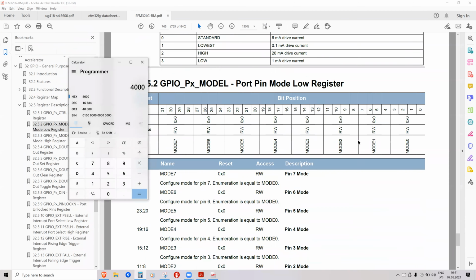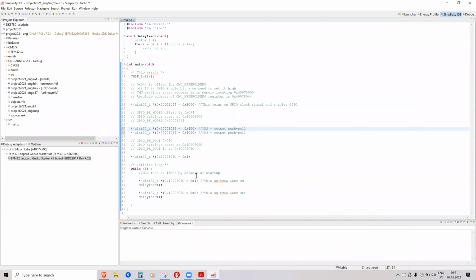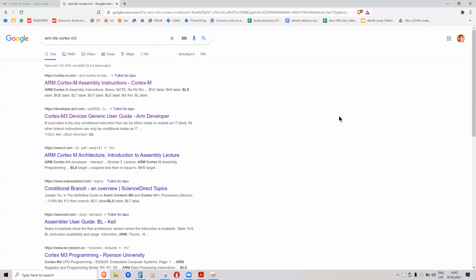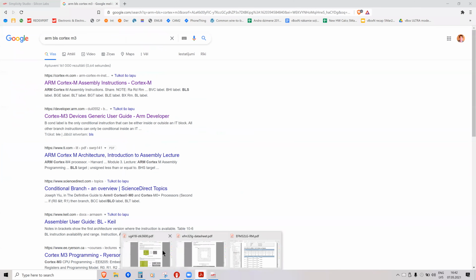And the second option is you can write it this way, but you need to write or equal to 0x4000. In C programming language, this or equal means leave all the bits inside this register as they were originally, but in addition to those which are already set, you also set this one bit high, which is bit number 14. Sorry.